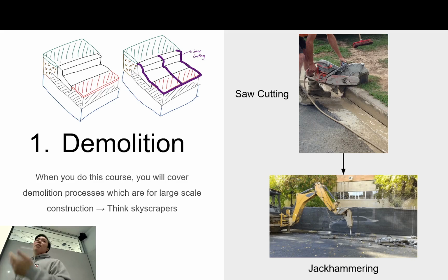Another thing is dust management. Concrete is quite toxic in its powdered form, right? The cement is made from silica, or has silica dust in it. And silica dust can cause silicosis and can give you lung cancer, basically, right? So if you know anyone who works in the tunnels, they have to wear masks all day because of the silica dust from the rock blasting, right? Concrete's the same. That's why you see people wear respirators when they're mixing concrete, okay?